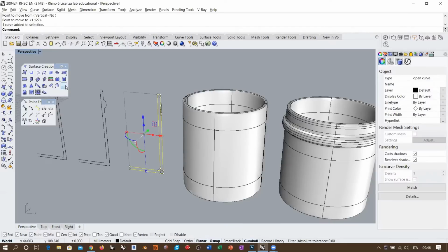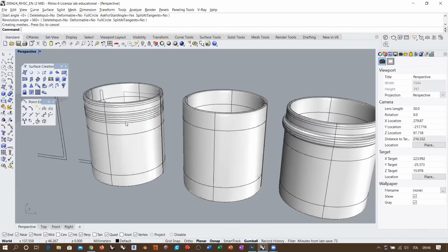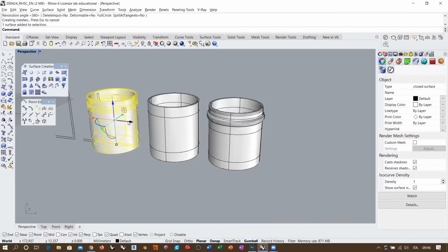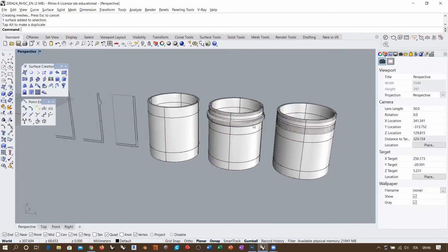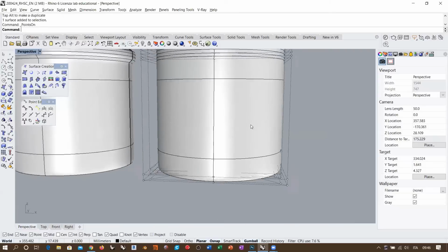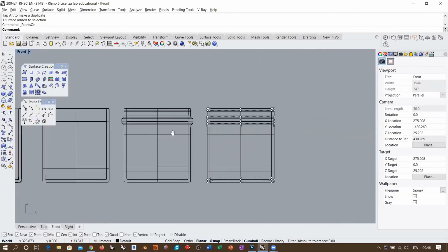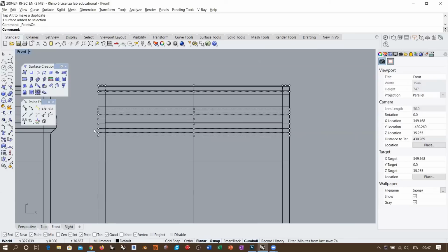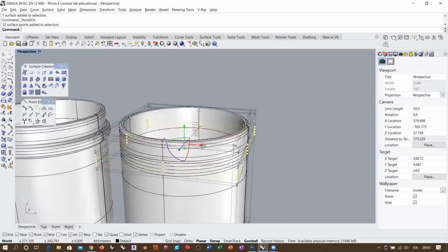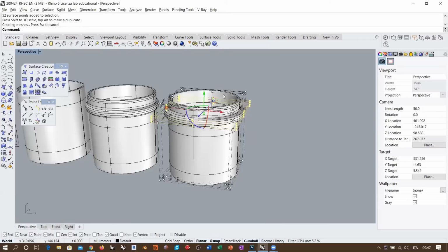So if I revolve this thing around this axis, even if it is not deformed, I already have the correct topological conditions for creating this kind of deformation. So I can do this once I have created the revolve. I can go into the front viewport, have access to this set of 1, 2, 3, 4 control points. And I can do exactly the same thing after creating the revolve surface, okay?